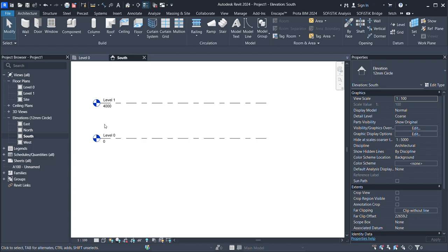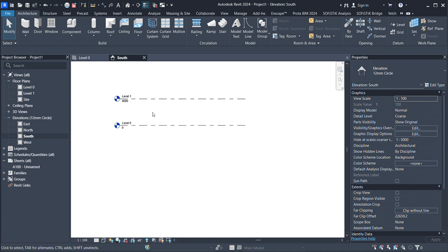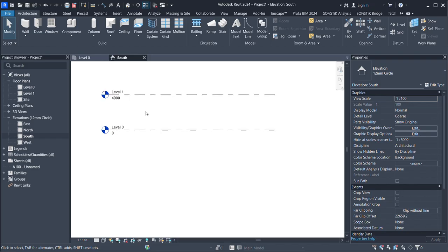So the building that I'm going to work on is a single story. That means I'm not going to add a lot of levels to it. So it's a single story that I'm working on. So I'm going to set my levels. Because I'm producing a plan and architectural drawing, I have to include my foundation, my ground floor, my ground level, and also my roof. You can decide to include the ceiling level to it, but I'm not going to do that.